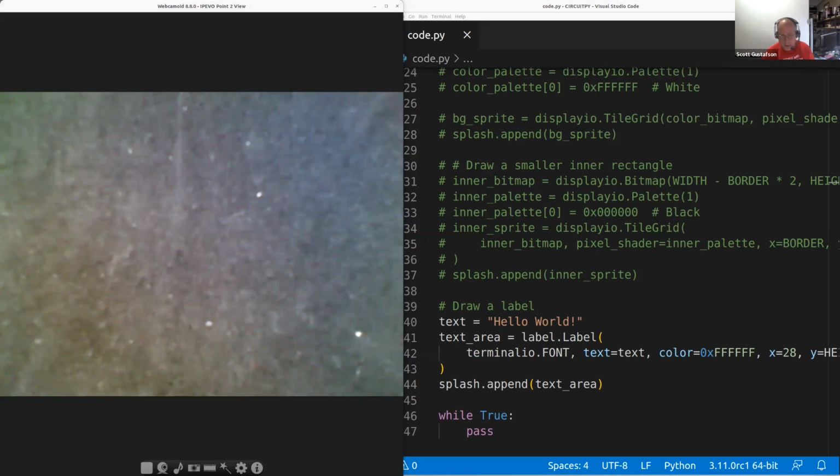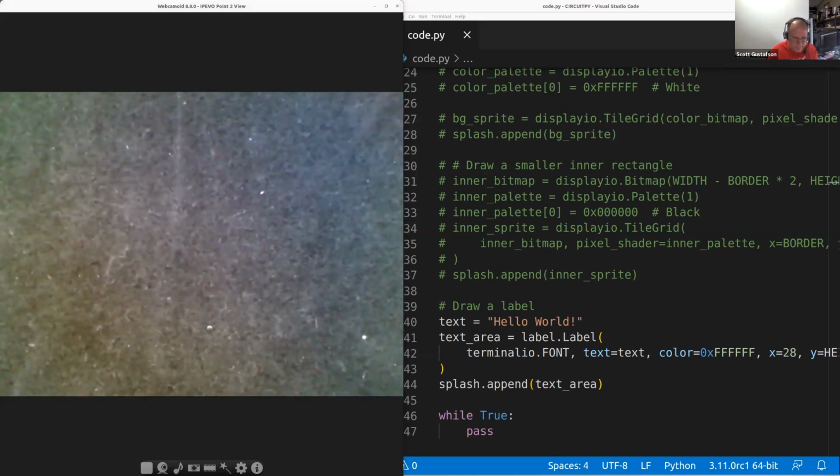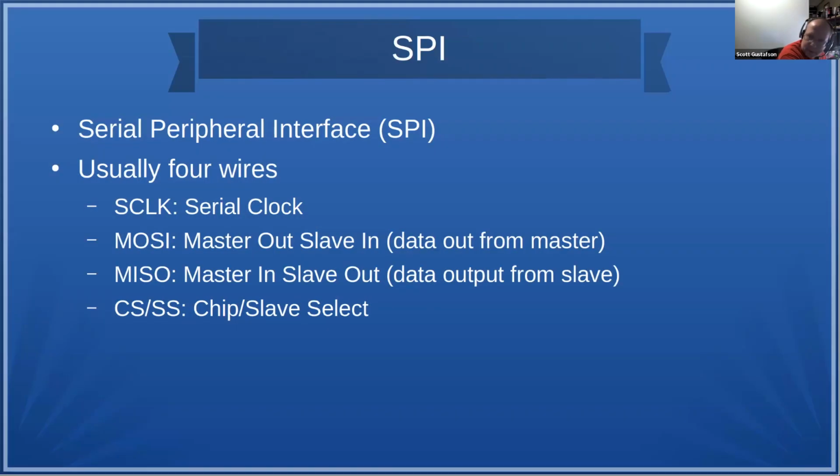All right. So the other interesting displays are on SPI. As you start doing a whole bunch more I2C stuff, you'll find your I2C bus gets a little crowded, and sometimes it slows down because it's trying to display things, also trying to read sensors and other things. Well, SPI is actually much better for putting your display on, and you can have full color displays.